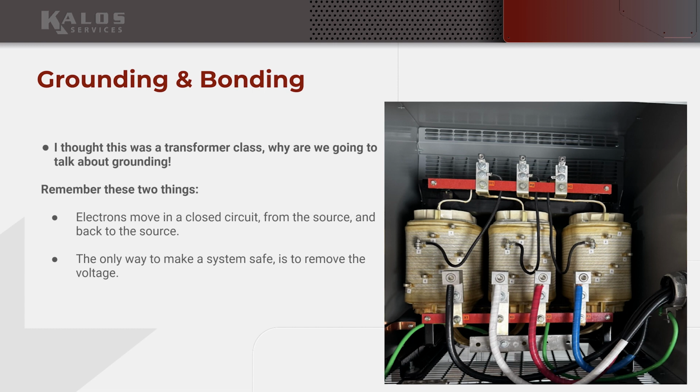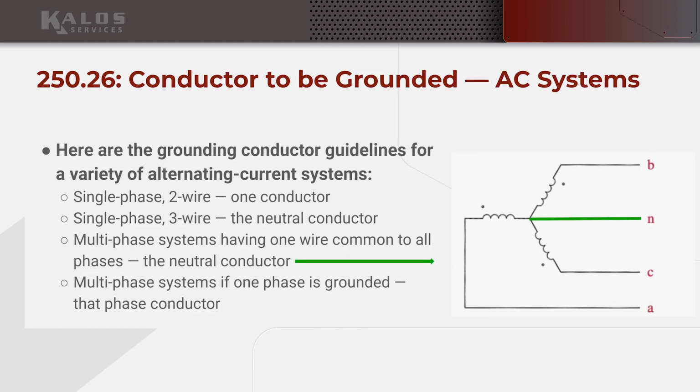So this is a three-phase transformer, Y connected. We can't see in the photo, but one side of these transformers is terminating to each of these lugs. And then our XO terminal has the center point of each of these coils behind it connected to it. That's our neutral, and we're also grounding that point in order to close the circuit so that we can get fault current back to the source, pull enough current to trip an overcurrent device. So this is just the diagrammatic representation of that to show where your ground connection terminates. It's at that center point here, and this is for a Y-connected system.